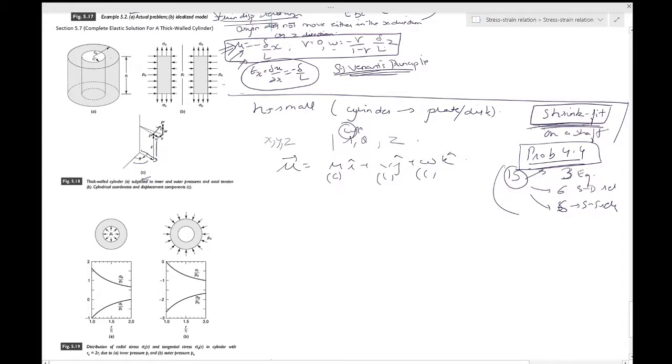So you have that part very well defined, and the method is exactly the same as you have used in the Cartesian system. You will take a point, an element. This time the element will have cylindrical coordinates, and then you must apply the force balance and the moment balance. There's nothing new about that. It's just that it will take slightly more time. One reason is that you cannot just replace x, y, z with r, theta, z. You can always say, we already know the Hooke's law, we already know these 15 elasticity relations in x, y, z.